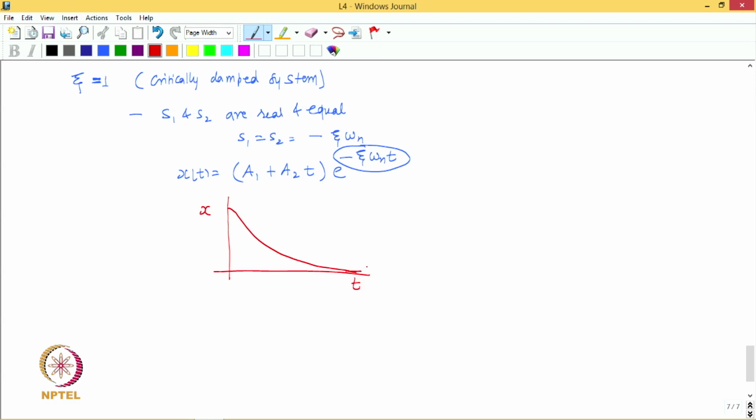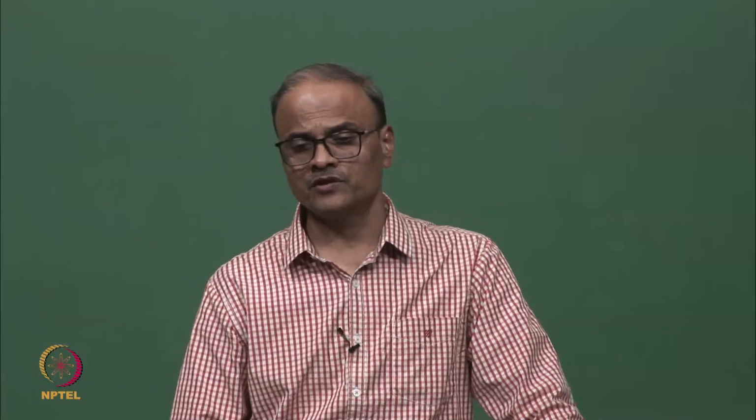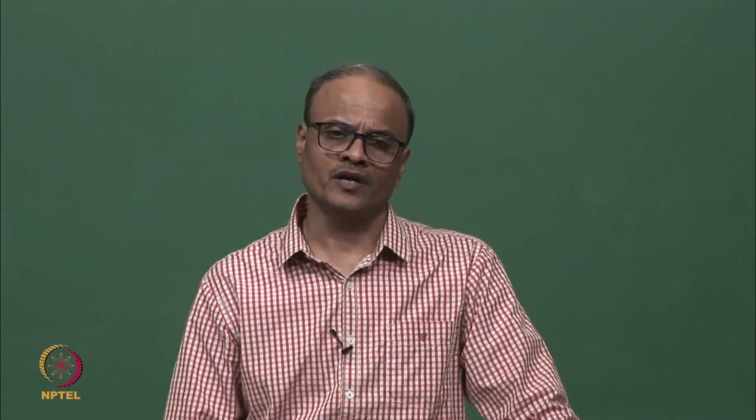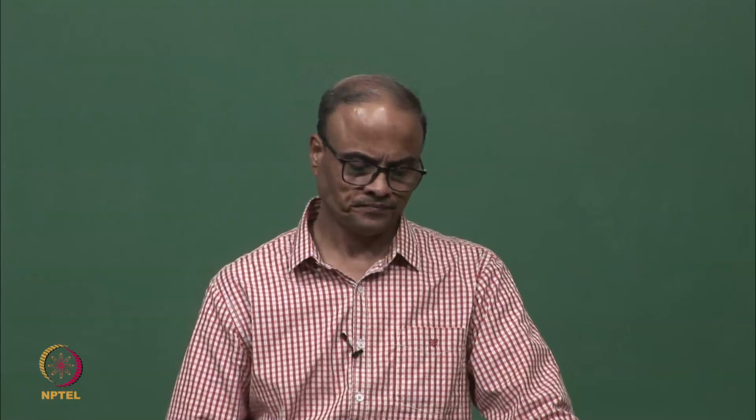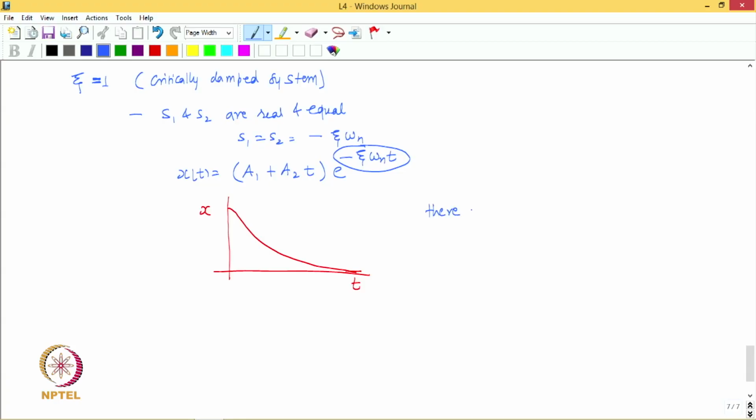Theoretically it takes infinite time for the displacement to reach the mean position 0. But in practice, in addition to the viscous damping which might be there, there may be other damping mechanisms present, because of which the system would come to rest at the mean position in a finite time. So, here also again we observe that there are no oscillations, and the response decays exponentially.